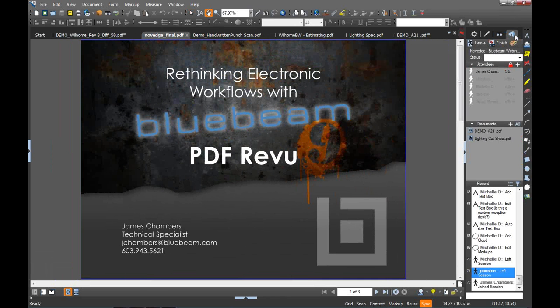If you had a regular session with somebody, so you constantly invited them, when they end the session or leave the session, Bluebeam simply turns into a viewer and a printer on their machine. The next time they join your session, all of the features and functionality are brought back to life, giving them the ability to mark up all the documents you want them to. So yes, it will stay on their machine as long as they keep Bluebeam on there.